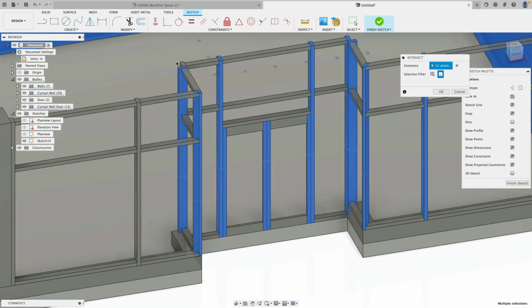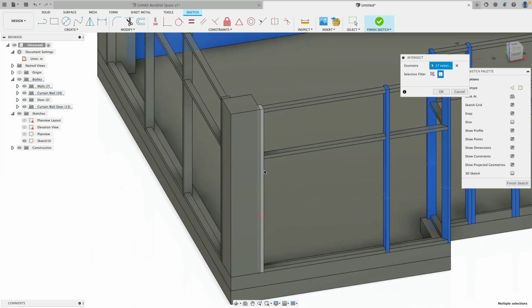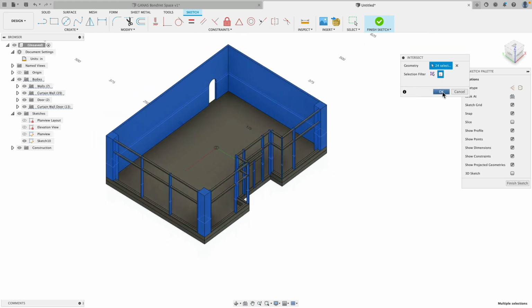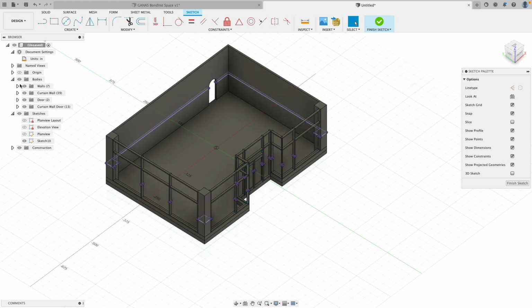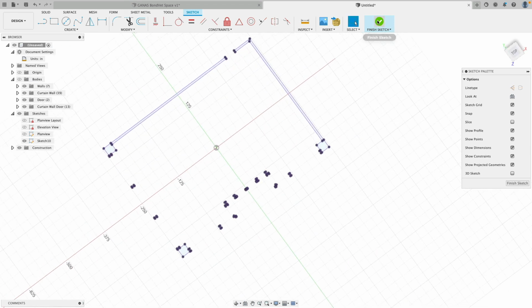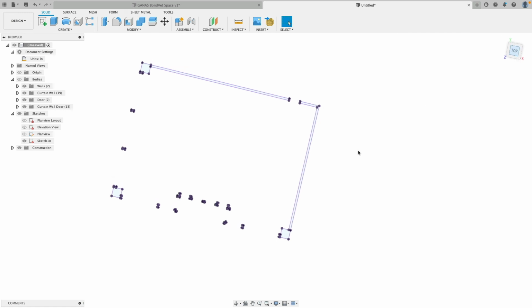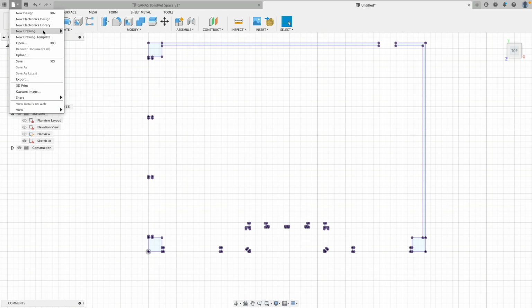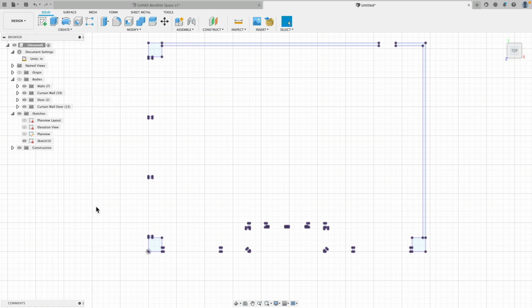So it finds where the sketch, where it is positioned, intersects these other elements, and then where it does. And I select them and I click OK. I get this plan or the sketch for me. Cool. So I can use the drawing module if I want to. Create a new drawing from it. If I then want to detail it all inside Fusion, I can. If I, however, just want to create sketches based on the architectural model or the geometry I modeled in general, this is then the way how to do it.